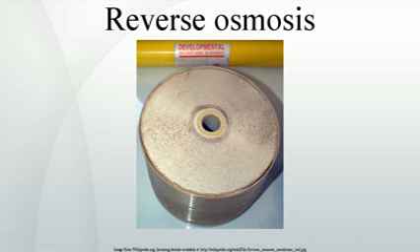an activated carbon filter to trap organic chemicals and chlorine, which will attack and degrade thin-film composite membrane reverse osmosis membranes, a reverse osmosis filter, which is a thin-film composite membrane, optionally, a second carbon filter to capture those chemicals not removed by the reverse osmosis membrane, optionally an ultraviolet lamp for sterilizing any microbes that may escape filtering by the reverse osmosis membrane.